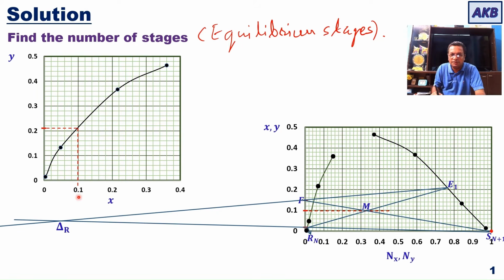Now with the help of this x, I am going to locate point R1 on the ternary diagram. So when I come back to the ternary diagram, point R1 will be located at x is equal to 0.0099. So it is over here. And I will locate point R1 on the A reach part of the curve. So point R1 will be located over here.